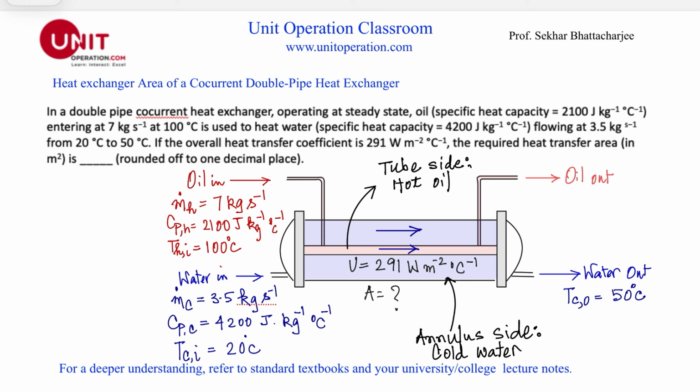So if we use the co-current heat exchanger, here what happens is the hot stearic acid comes in and meets the coldest water. So there is a high temperature gradient here and very fast cooling. As it cools, the stearic acid gets cooled, but the water is also getting heated up. So here the water is hot, and this does not lead to solidification or deposition.